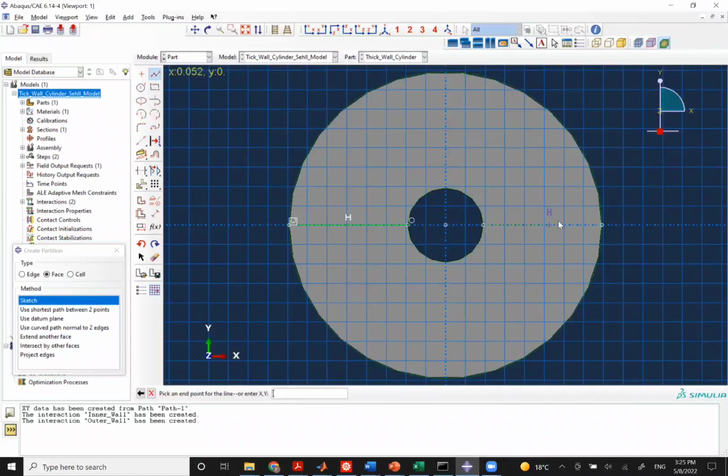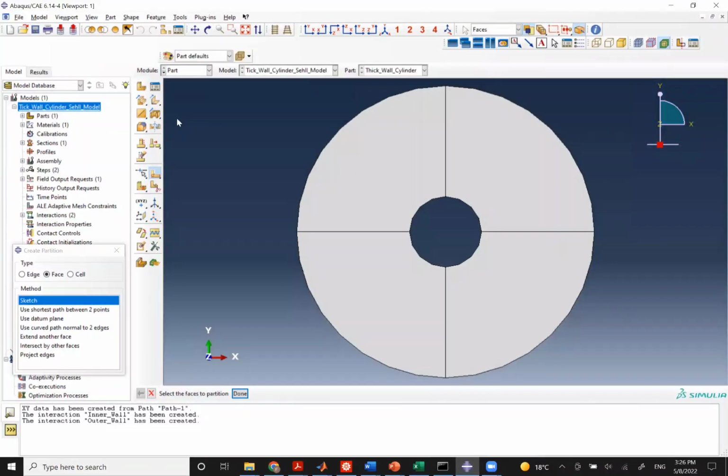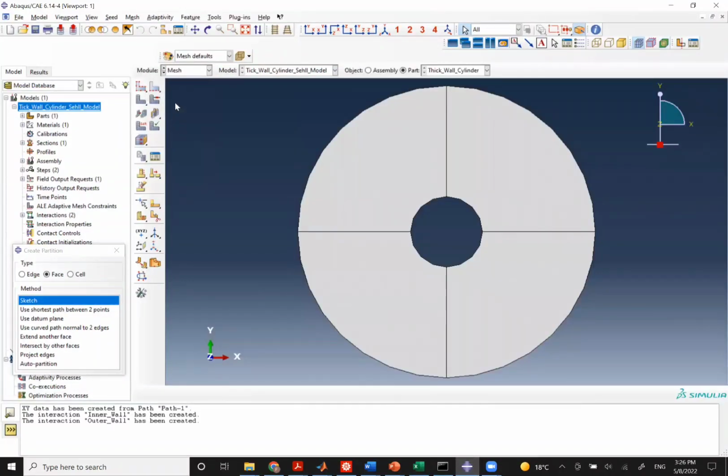And a line here. Two more lines and we're good to go. So the structure is very simple to make it a structured mesh. So that's why I want to show it. And it's good to see how you can turn these problems into structured mesh, because that reduces complexity and gives you better resolution with a smaller number of elements.